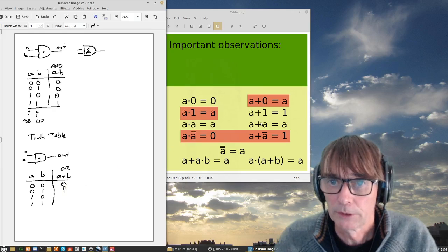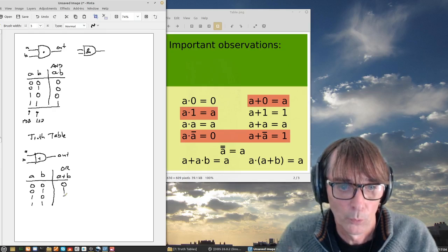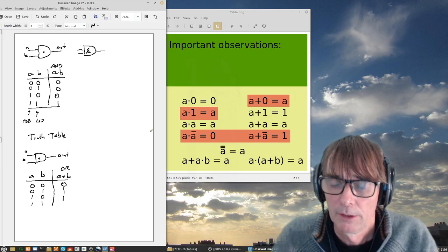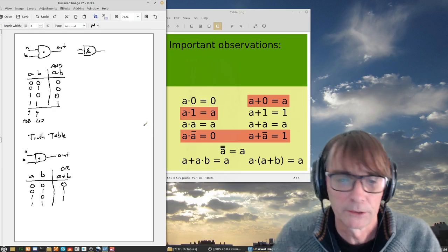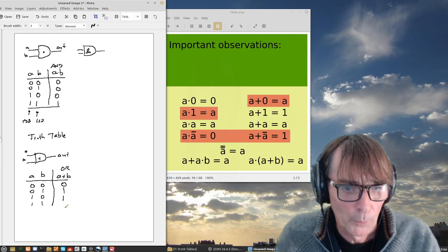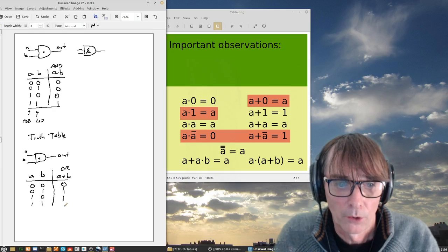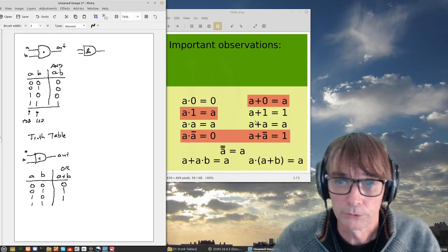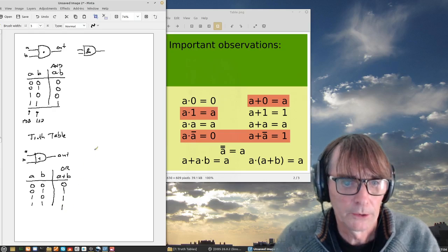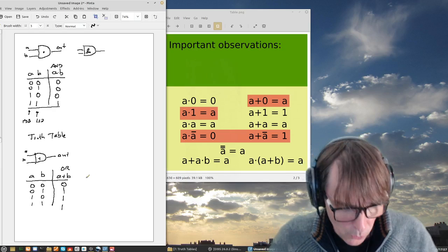And in the same way, of course, I can exchange these two and then I get 1 or 0 equals 1. As you remember, the laws, Huntington postulates, you can exchange the two operands and the result at the output will be the same, always. So now you get the last one, 1 or 1. What would it be? Well, I will substitute in this one, for instance, 1. So 1 or 1 equals 1. So this is then the truth table for the logic gate OR.